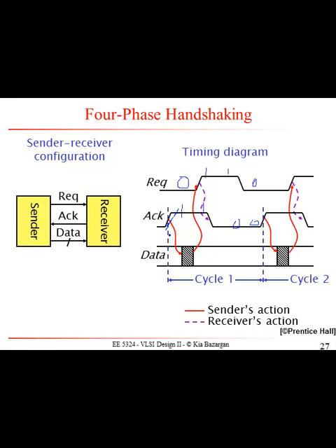And of course, when you think about these handshaking events, don't just think about the pipeline event. You could potentially have a data buffer here, and maybe you're talking about a network on chip. It could be anything, right? A data transmission could take some time, and it doesn't necessarily have to be just one data sent to a register. Once you receive the data, and you finish sending the data, you would request the data to be processed, and that's what the sender is going to do.